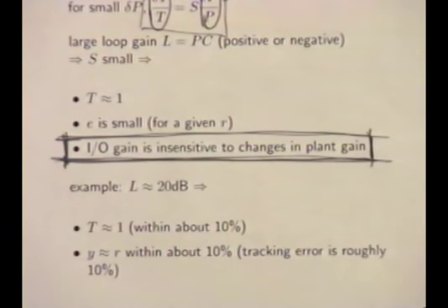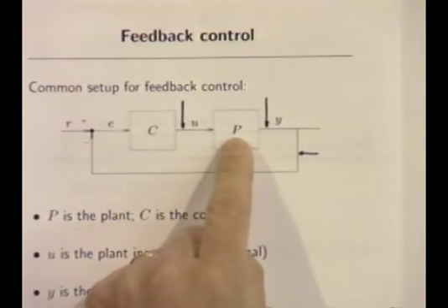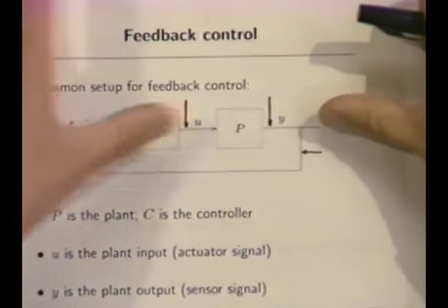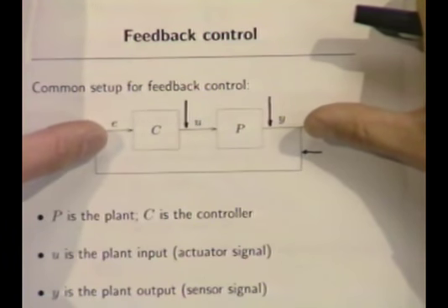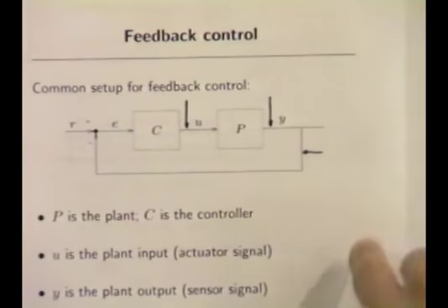There's a question. What is the distinction between your closed loop gain and just your normal loop gain? People refer to P as the open loop gain of the system. Is that the same thing as just normal loop gain? Your loop gain here would be PC, right? And then the closed loop gain from R to Y is PC over 1 plus PC.